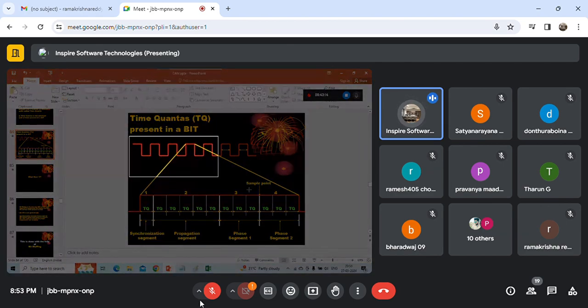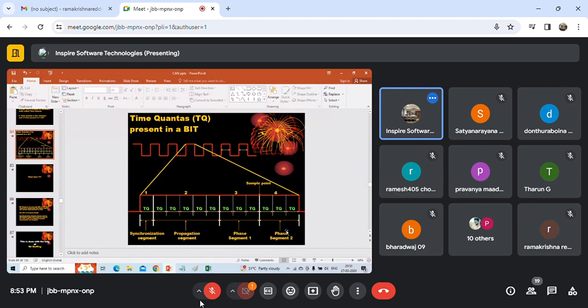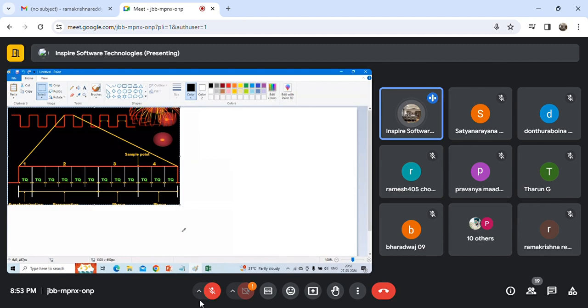I was telling you that for synchronization, it will add the sync bit or stuffed bit. I don't know how many of you remember. Let's say it is going like this. For example, one controller is like this, another controller is like this. If it is going with some offset, when it sees the signal change on the data line, the start bit is coming, meaning a dominant bit, so 0 will come, right?